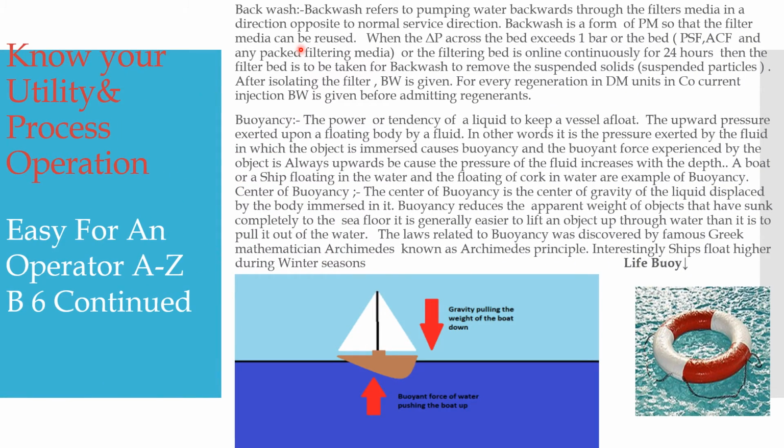Now we can see the next word starting with B, backwash. Backwash refers to pumping water backwards through the filter's media in a direction opposite to the normal service direction. If the service is from top to bottom, then backwash is from bottom to top. Backwash is a form of preventive maintenance so that the filter media can be reused.